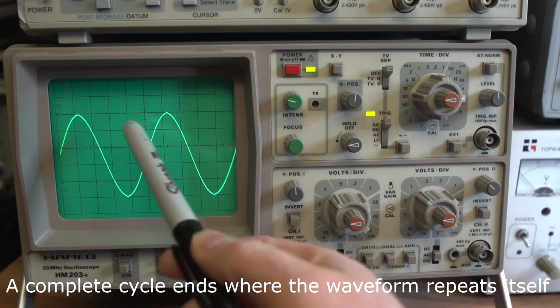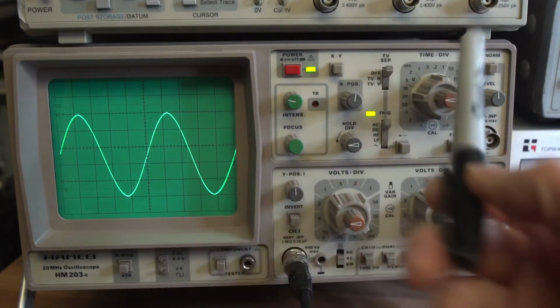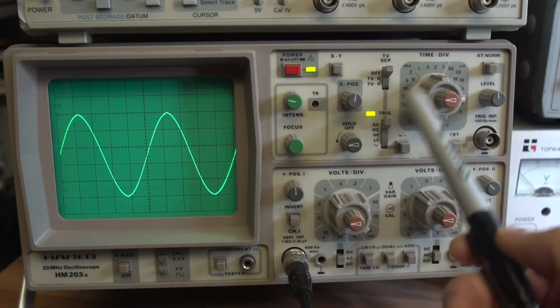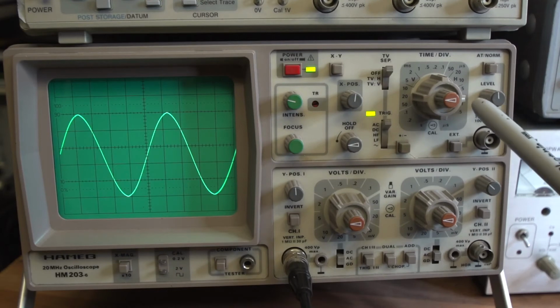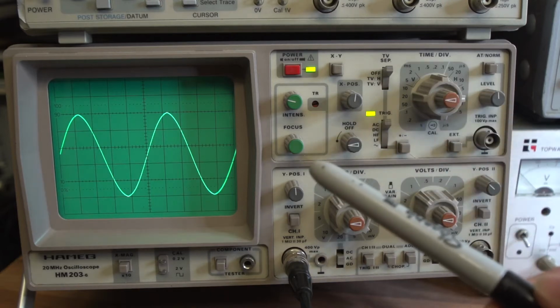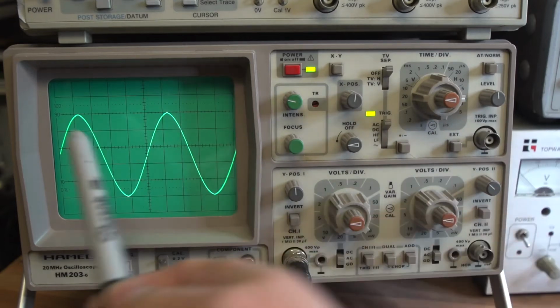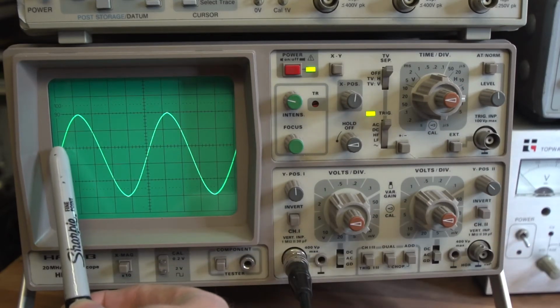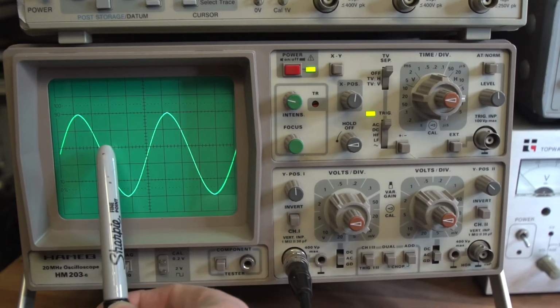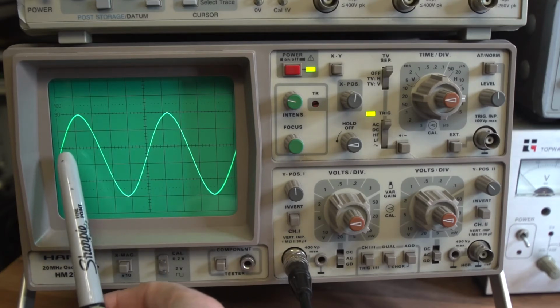Now again, like what we did with the amplitude and the voltage measurement, you can measure time using the time-base control. And the time-base control, in this case, is set to 2 microseconds per division. That's pretty quick. It's much faster than we had it before for the speech pattern. So this one is 2 microseconds. It takes that long for the dot to go from there to there, there to there, there to there. It's all 2 microseconds. So if you look at the waveform, how many graticule squares are we dealing with here?